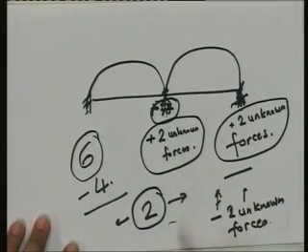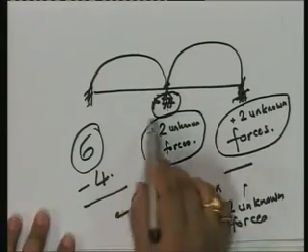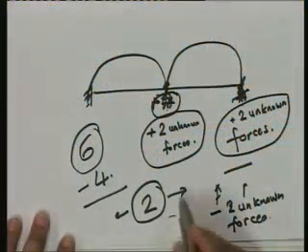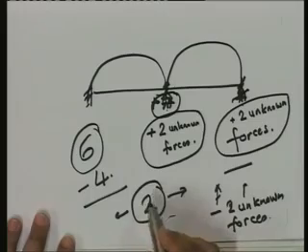A cantilever. And we know that a cantilever is a statically determinate structure. So, by removing 2 unknown forces, I have made it into a statically determinate structure. So, what is the static indeterminacy? Well, 2. Either way, you get that this is a 2 degree statically indeterminate structure.